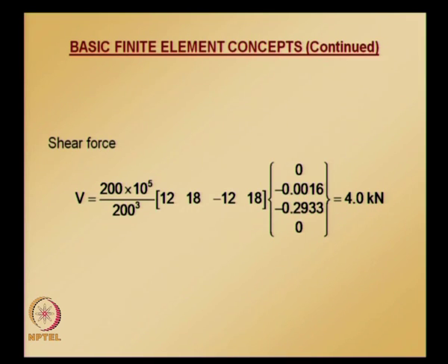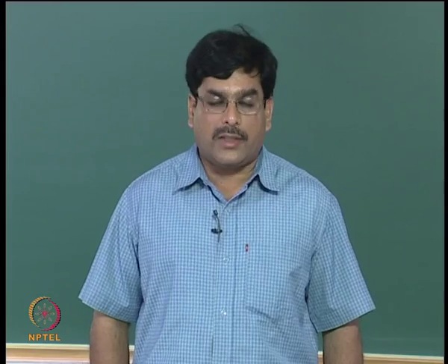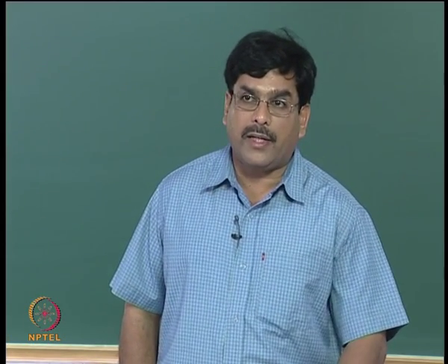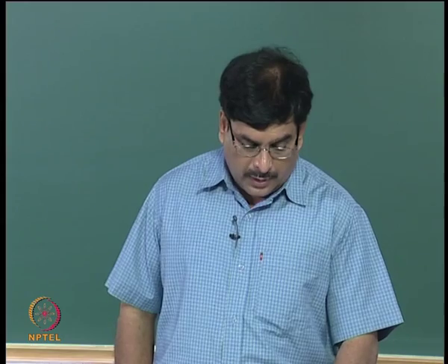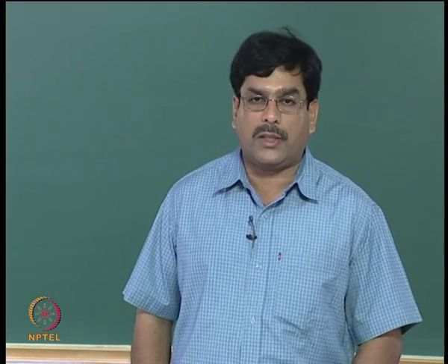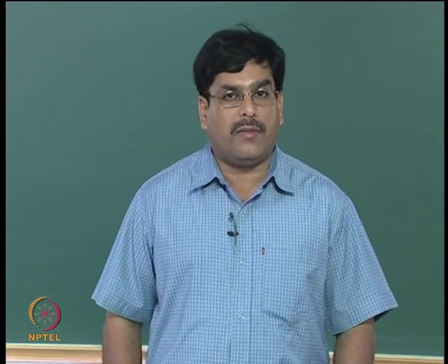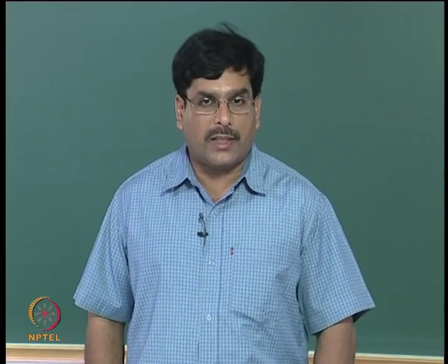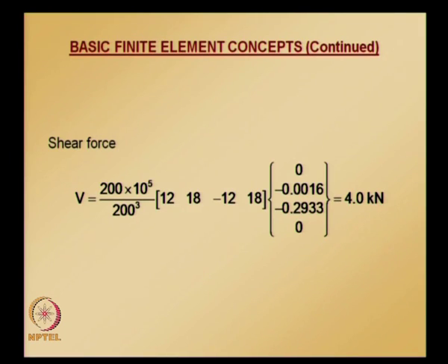Now please note that whatever shear and bending moment we calculated, they are all internal shear and internal moment values. So whenever we try to draw this or put this in the form of a plot, we need to follow sign conventions corresponding to the internal moment and internal shear that we started out with.